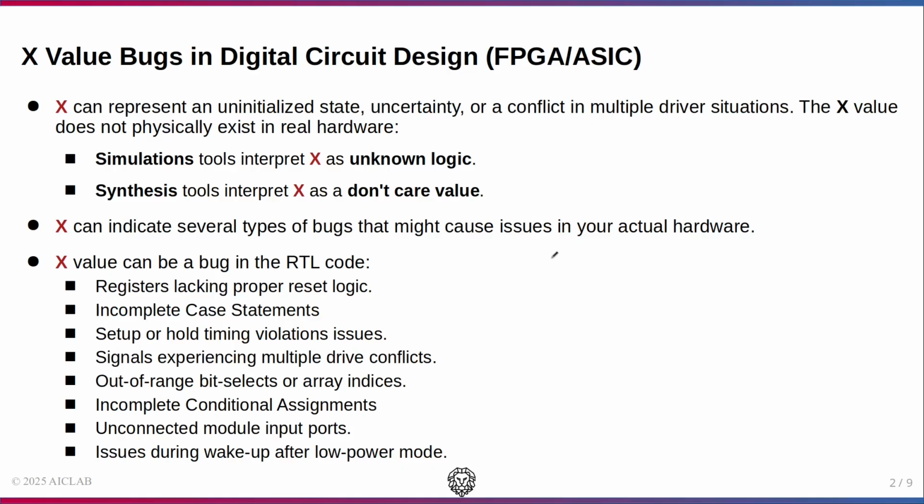The simulation tools interpret X as unknown logic, but the synthesis tools interpret X as a don't care value. So the synthesis tools try to optimize the circuit. X can indicate several types of bugs that might cause issues in your actual hardware. In the next slides, we look at different situations where the X value introduces bugs.